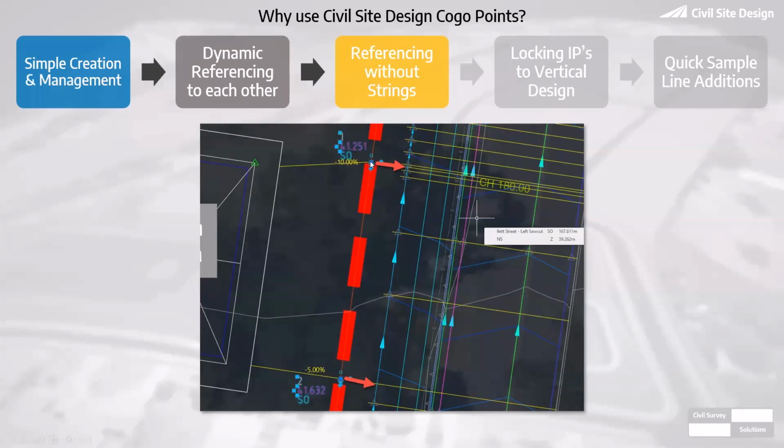There are Cogo Points here and here, and they are referencing the elevations of, this could be a building slab around the edge, or it could be a car park. You can see they're 5% and 10% from that building slab. We can then design this string of this boundary here to be either using those elevations of those Cogo Points, or we can adjust the elevations, but using them as a reference. So I'll show you the example with that, just trying to keep this nice and simple today to show you how you can operate them in two separate areas.